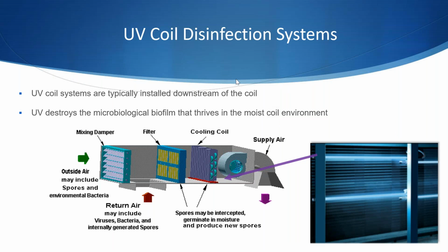So we get asked a lot, where's the best place to put it? The answer is always, what's the goal, right? Someone comes to you and says, I want to build a building. What are we trying to do here? So with the UV system, you find out what your goal is. Are you just looking for cleaning coils? The answer in the last year has changed almost exclusively to no. I want to provide airstream disinfection as well.